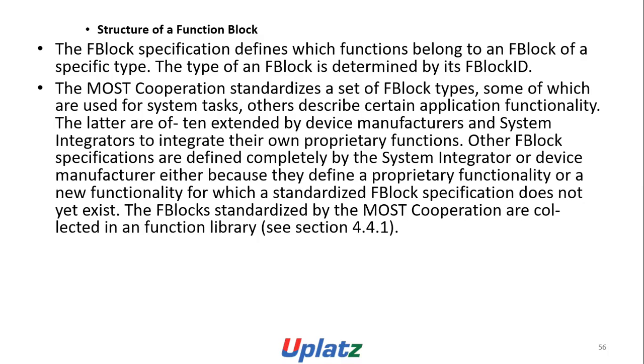The MOST Cooperation standardizes a set of FBlock types, some of which are used for system tasks. Others describe a certain application functionality. The latter are often extended by device manufacturers and system integrators to integrate their own proprietary functions. Other FBlock specifications are defined completely by the system integrator or device manufacturer, either because they define a proprietary functionality or a new functionality for which a standardized FBlock specification does not yet exist.